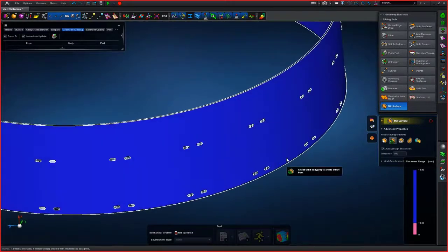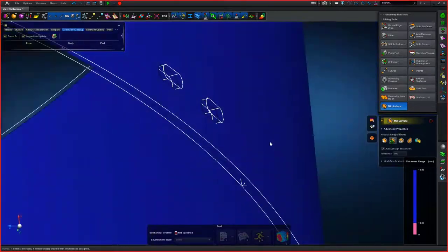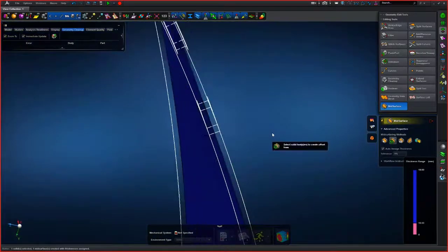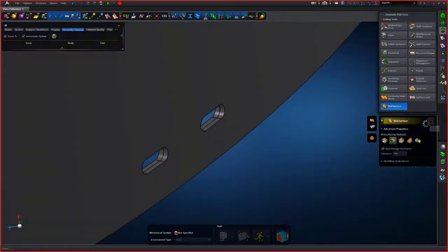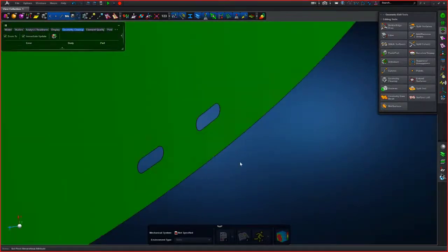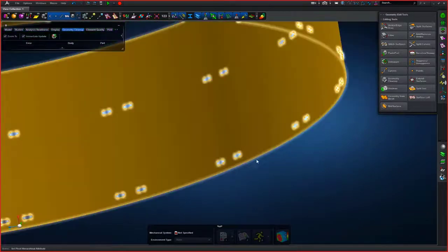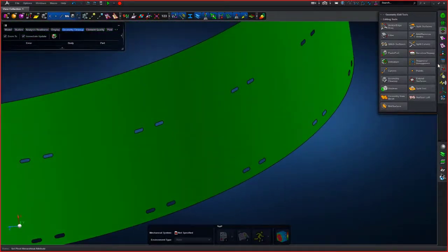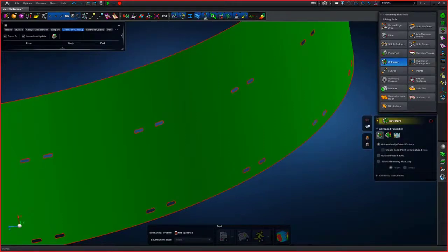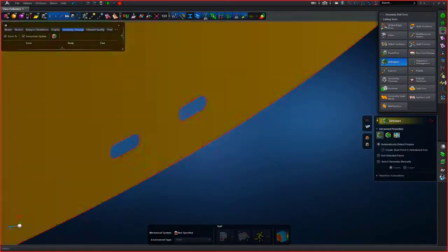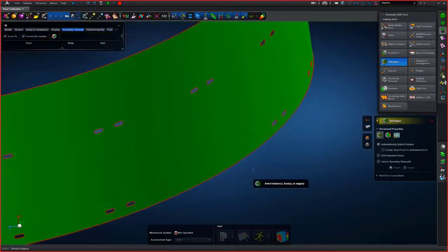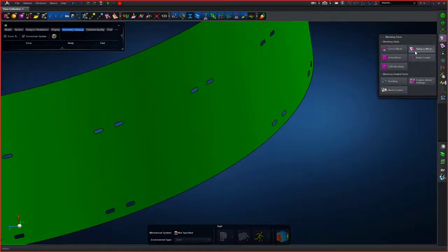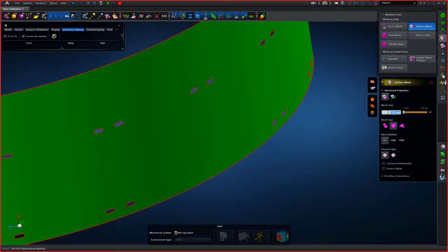And there indeed, we have a mid-surface created right at the middle of the solid, with the thickness automatically assigned. And just while we are here, I'm going to quickly show you another feature that not many people are aware of, and that is the defeaturing tool for special features like this. Now you could at any stage select them one by one to get rid of them if they are going to be a nuisance in your FEM.